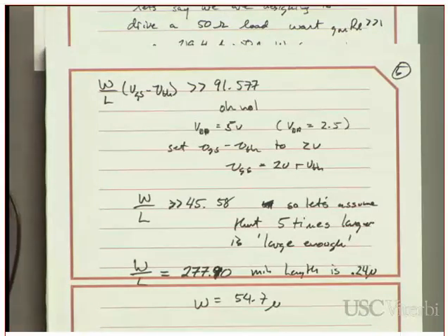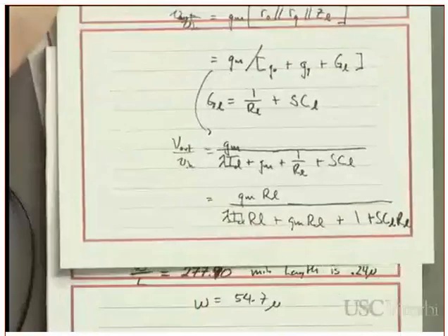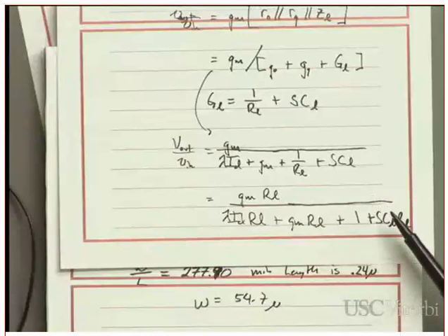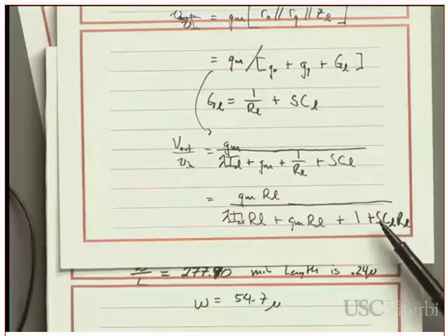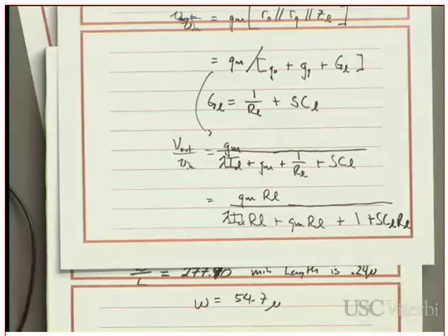Well, you can go back and look at your input impedance or your output impedance, or both, from last time, or your transfer function, and figure out if you're getting a mismatch as the frequency goes up. If we go back to this one, as my frequency goes up, this number is going to become more and more significant, so it's going to play a larger and larger role. So I might not then be in a range where I can start ignoring this thing, and I have to take it into account. But that tells you kind of what might be affecting your circuit.